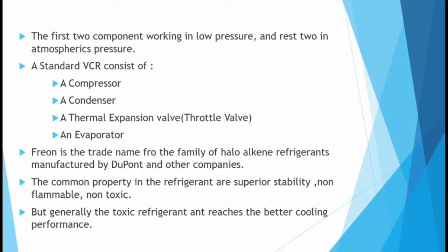From the expansion valve, the working fluid is fed to an evaporator where the low pressured liquid starts to evaporate into the gaseous form. The temperature of this medium remains the same as the heat absorbed is in the form of latent heat. The final stage or phase of the refrigerant medium coming out of the evaporator is gas. This gas is again fed to the compressor and thus the cycle repeats.